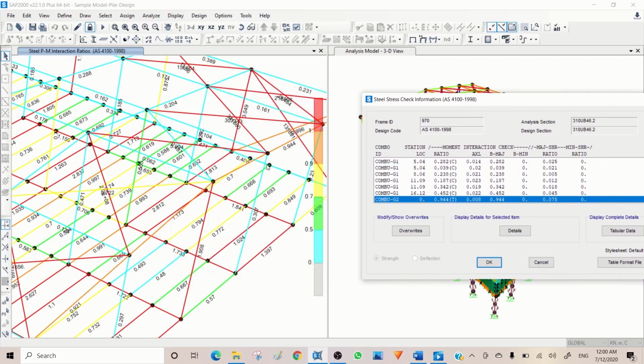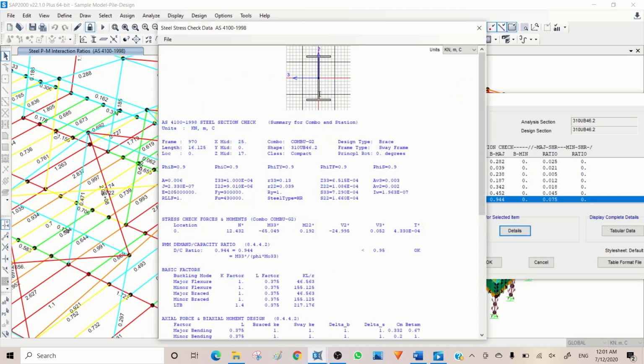The reason is, if you remember, we designed these wall post elements in the way that they are not taking axial load. That means those beams are being supported by middle columns, but these side beams are not being supported by wall posts. That's why they have higher stress. So let's check the detail and see what we have here.